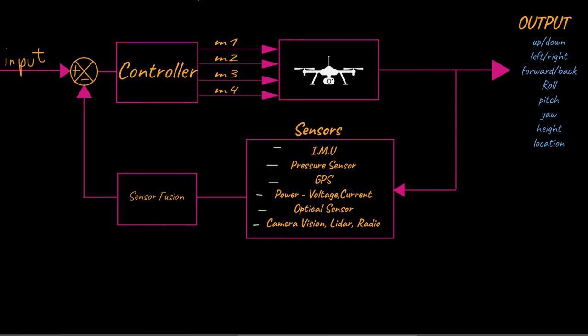This is then fed to the sensor fusion algorithm. And the sensor fusion algorithm should tell you exactly what the orientation of the quadcopter is. It should tell you whether it's moving, whether the quadcopter is at 30 degrees, 40 degrees with respect to the Earth on its x-axis, maybe 20 degrees with respect to the Earth in the y-axis. So it needs to give you the high-level orientation of the quadcopter. So that's what the sensor fusion algorithm will do.